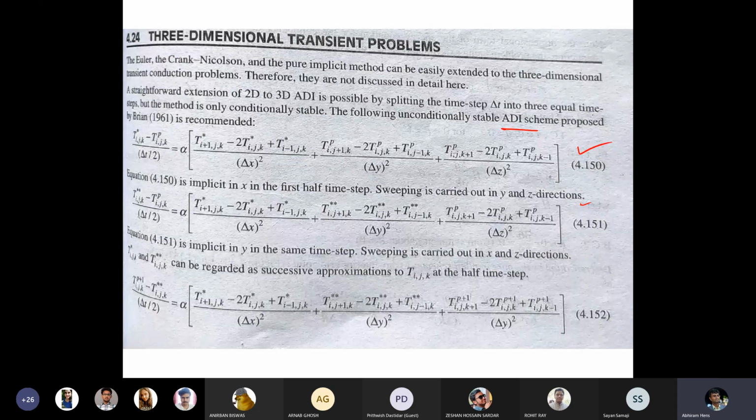That I am not going to cover, because the ADI scheme etc. will help you to get advantage of stability etc. It can be understood in little more detail only if you start working on this particular area. But I would like to show you how a 3D unsteady conduction equation will look after discretization. This is a 3D differential equation, and you see that now it is a pure algebraic equation. Now you have to solve it taking any particular method.